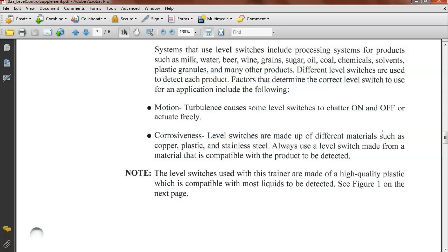Conductors are rated in the amount of amps they can pass. We call it ampacity. Insulators are designed to keep the push in, right? Jackets are designed based on what environment the conductor is going to run in. So sometimes your insulator and your jacket are the same. Sometimes they're totally different.